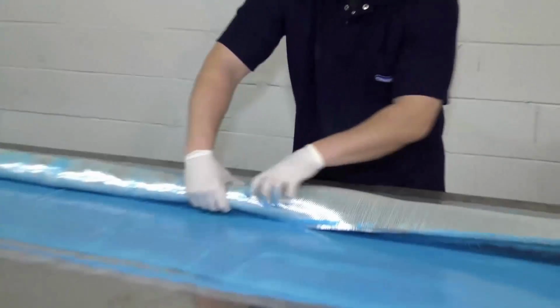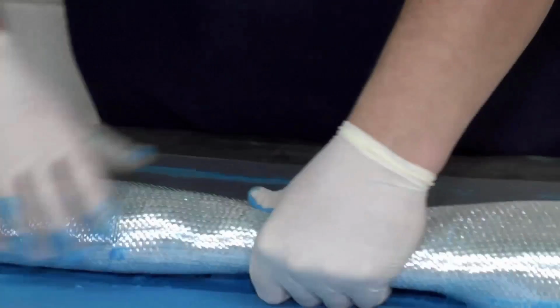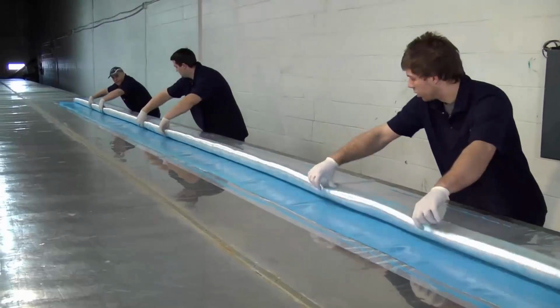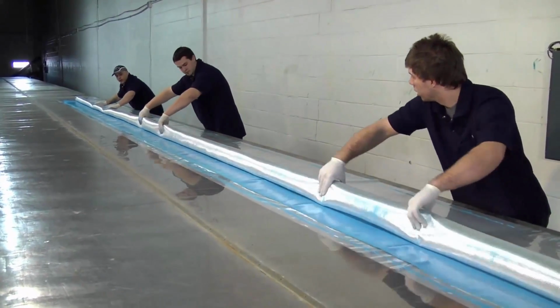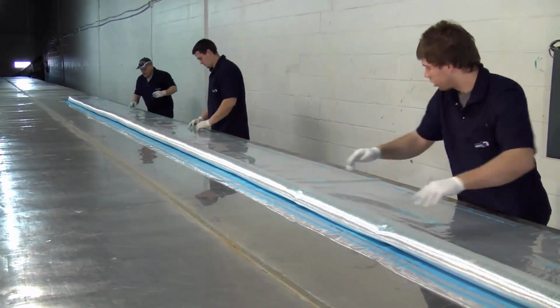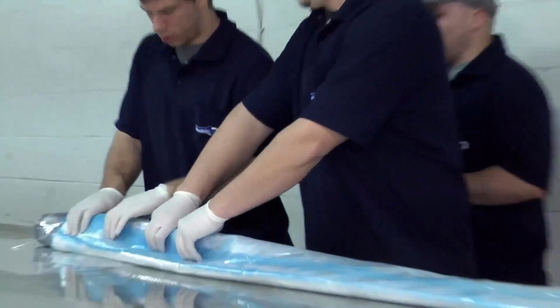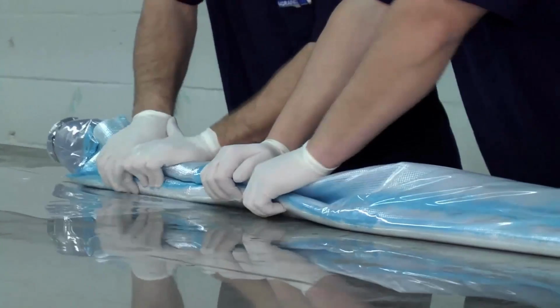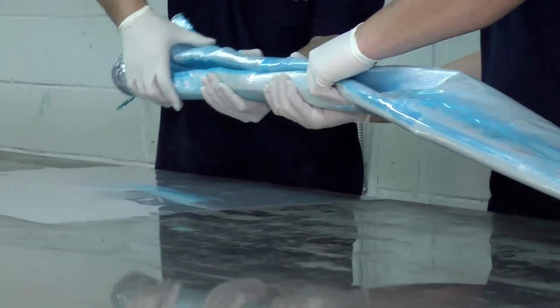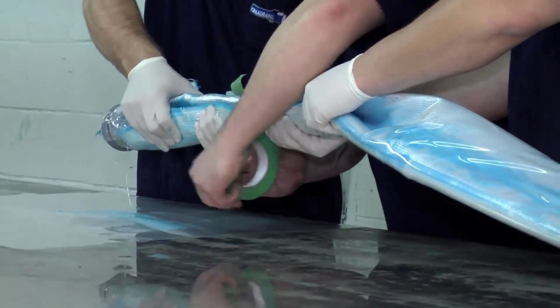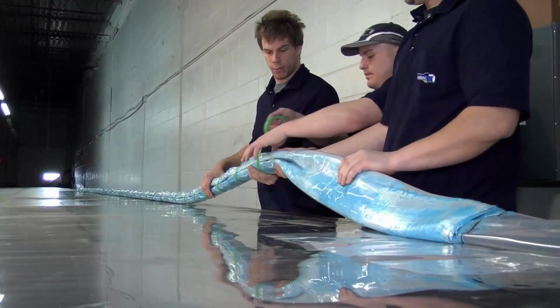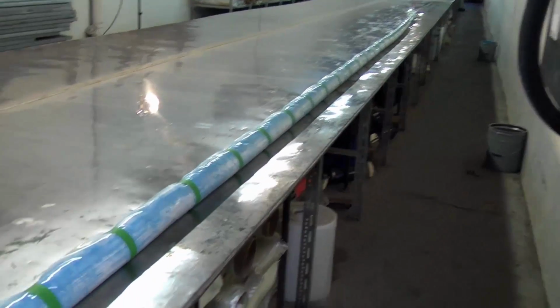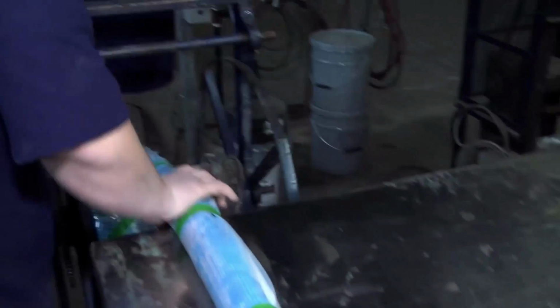Once that fiberglass is rolled over the bladder, we're going to roll it into another polyethylene layer. That's going to make it more watertight once the repair is in, and that's going to prevent the resin from going into cracks. So once that is wrapped, we're going to U-fold it to make it smaller. So you fold it and U-tape it about every foot, and then it's reeled on a big reel that is supplied with the equipment and taken to the job site.